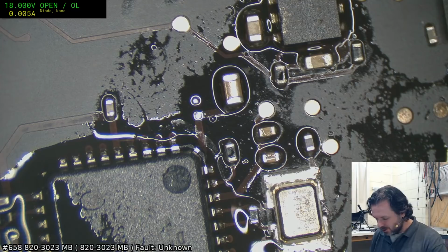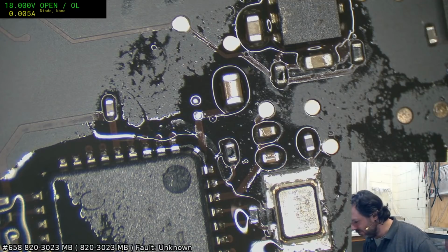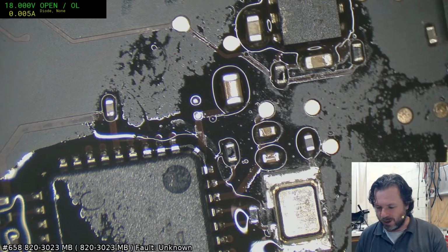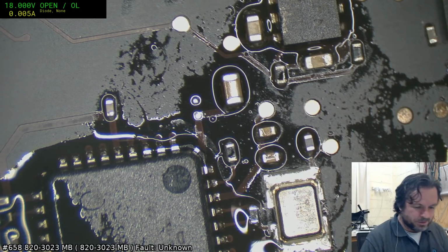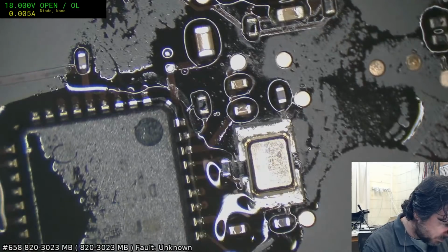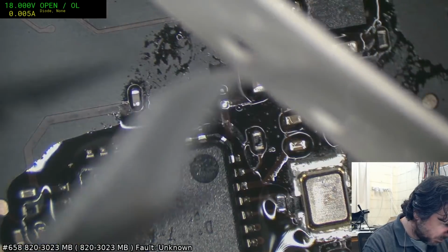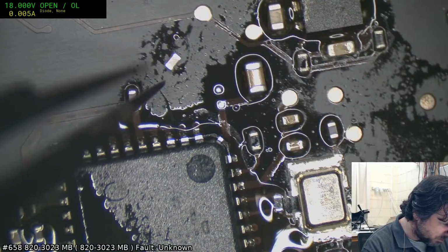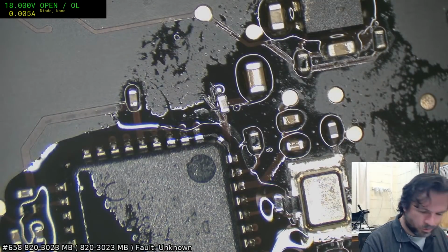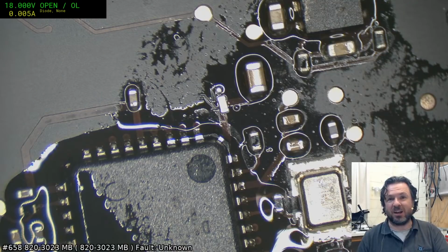Most of the time, there's no real computation done to work out what the actual required capacitance is for that line to make sure it stays stable. It's really just a case of, well, we built it, it seems to be working, and if you do get a glitch, then you pretty much just double up everything, or throw in a few extras until that glitching goes away.